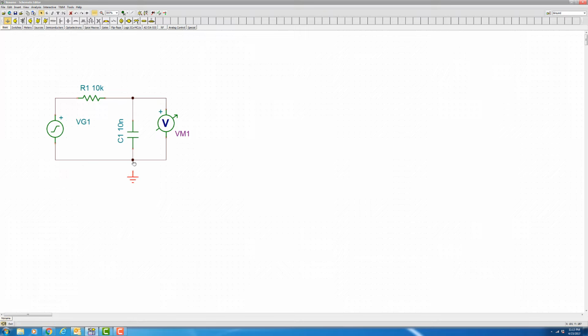So let's give our SPICE circuitry a ground. Use the wiring tool. Now SPICE will be happy. It has its ground. This is also always called node 0. So we have node 0, node 1, and node 2. Now we're ready to run it. But before we run it, what I'd like to do is add another voltmeter across the resistor. So I'm going to simply drag this over here. I'm going to connect a voltmeter so I can look to see the value across the resistor.